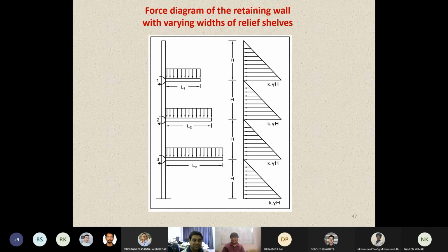Because many a times we tell that, okay, 5 reinforcement bars will be passing through. But when 5 reinforcement bars are passing through, when they're doing it in the field, if they're not able to pass through, many a times you will see they will curtail 2 bars somewhere and 3 will be put in. So those things are also a major concern, because the structure is now not so simple. As a simple cantilever retaining wall, it is not so simple anymore, construction wise.